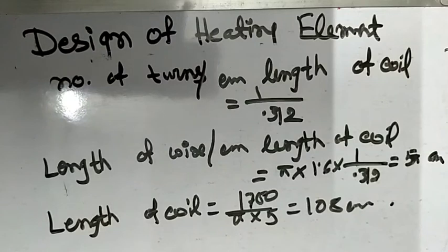Since the dimension of element and power of furnace remain the same, the heat production rate remains the same, and the reduction of charge temperature will increase the heat radiation rate, and this will therefore reduce the final temperature reached by the element.